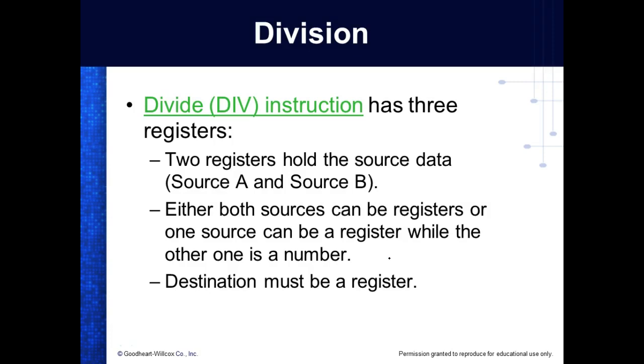Then we've got the divide instruction. It has 3 operands, source A and source B, right? I think source A is your, what's the column called, the dividend. B is the divisor. And your quotient, you're going to put it where you want to store it, right? One of the sources can be a constant, but the other one, they can both be addresses, right? You understand? Or one of them could be a constant, but the other one's got to be a variable. Everybody understand that?